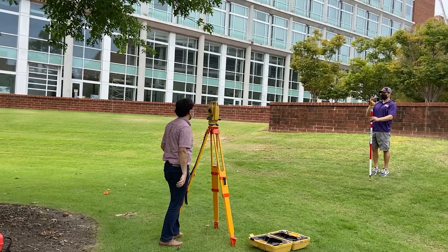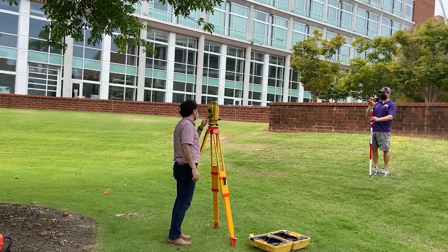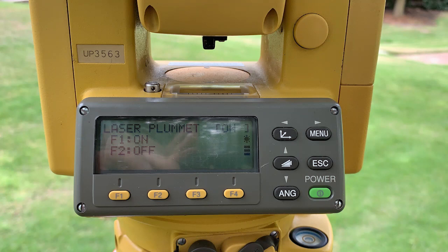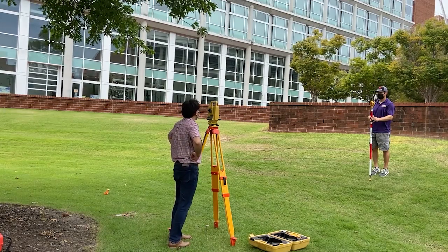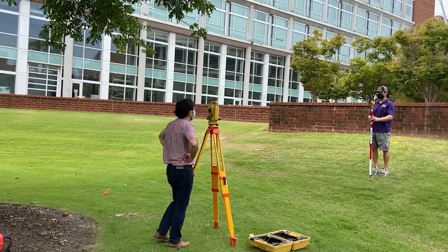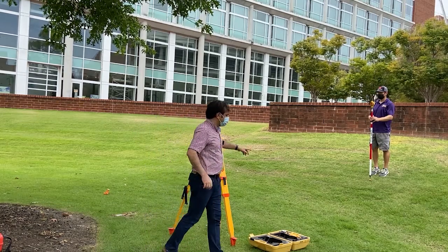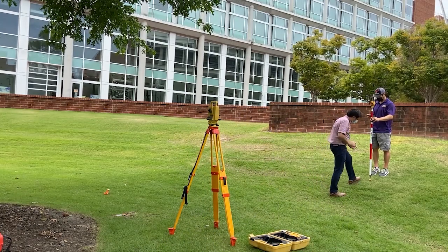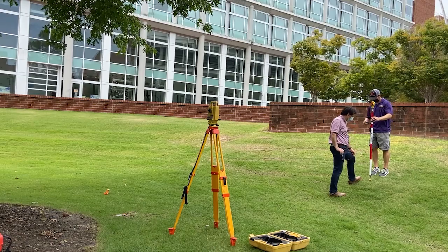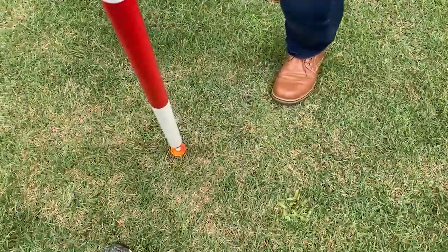Then the next step is to take the measurement. If you take a look at this total station, you see that it has on the right side 6 buttons, and the middle one on the left is like a triangle. So if you hit that one, it measures the distances and it gives you the horizontal, vertical, and slope distance. Before you hit the measure, you make sure that your rod person is holding the rod correctly. The rod has to be exactly on the point, as you can see here.